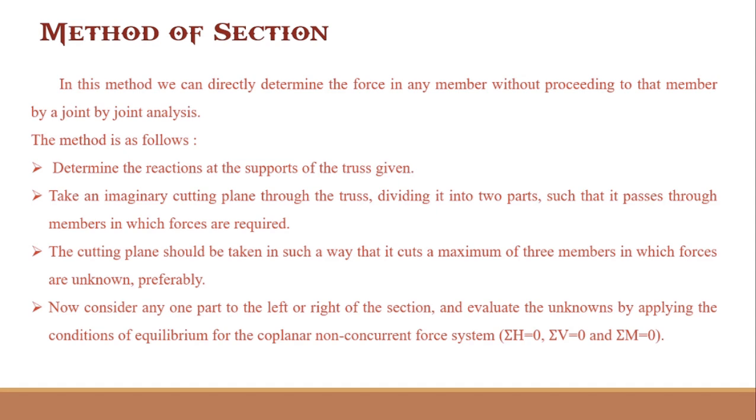Determine the reactions at the support of the truss given. Take an imaginary cutting plane through the truss, dividing it into two parts such that it passes through the members in which forces are required. So where the forces have been asked, we have to cut that portion so that we can calculate the forces at that point to solve this problem.